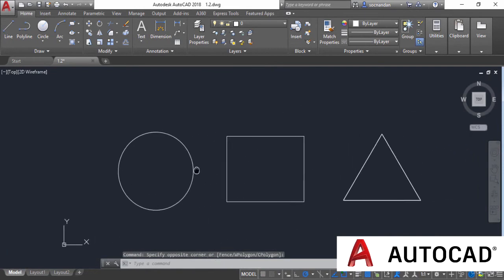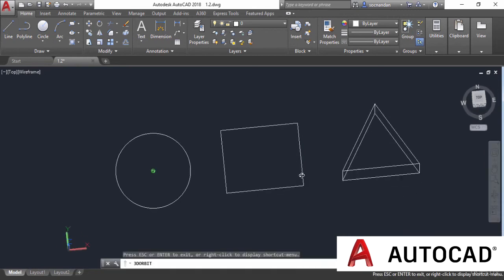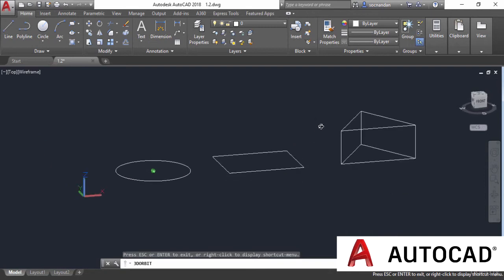We can also access the 3D orbit tool, and using the 3D orbit tool, you can see this drawing from X, Y and Z axis. So currently we are able to see this drawing from X and Y axis or from the top view only, that you can see here with the top view. But in order to see it from the 3 axes, or if you want to see the height of this drawing as well, simply go to this orbit tool from the navigation bar, select the orbit tool and now orbit your drawing just like this.